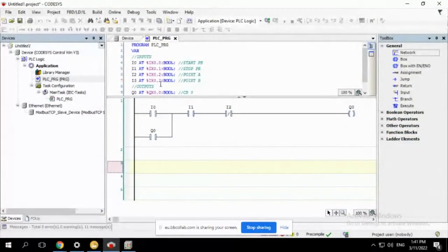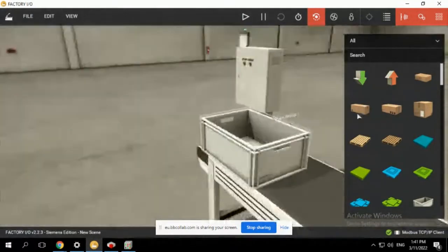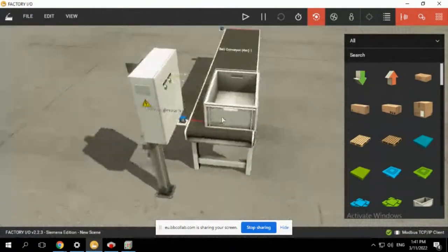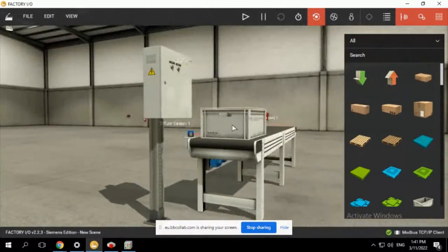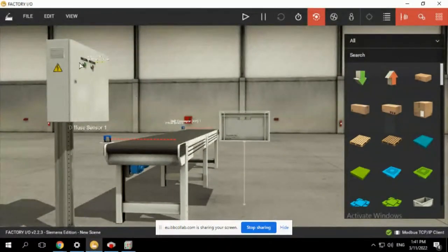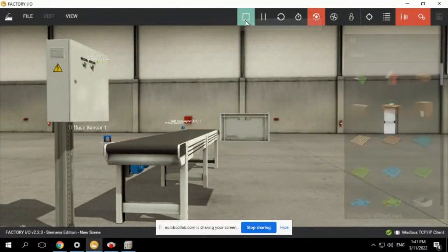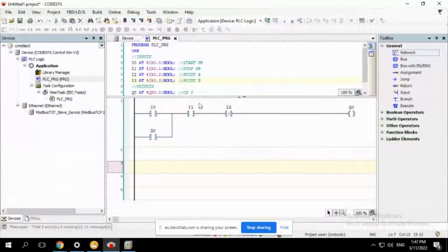So now this changes to 3, 3 point B, right? So the condition is that this must never run unless there is a crate in this location. Okay, so obviously, in order to demonstrate this one perfectly, we need to remove the crate and see what will happen. We can just say start. Now it will fall there. Then let's put our condition in our program.